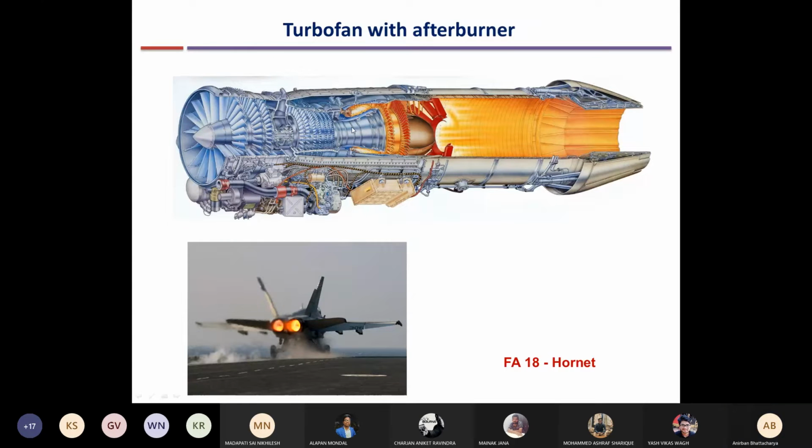the combustion products still have quite a high enthalpy, and if we accelerate them through a nozzle, it will be like a normal turbojet or turbofan engine. We will generate thrust. But because a very large air-fuel ratio is used, a lot of unused oxygen is still present in the combustion products here.